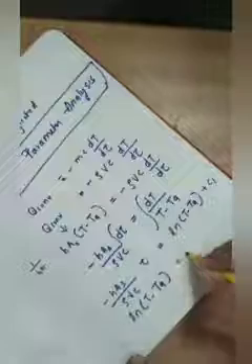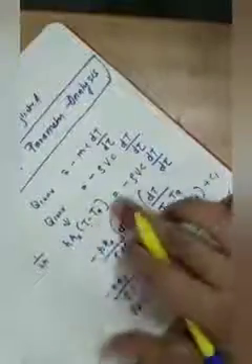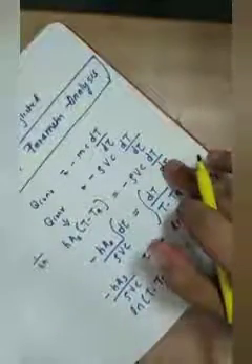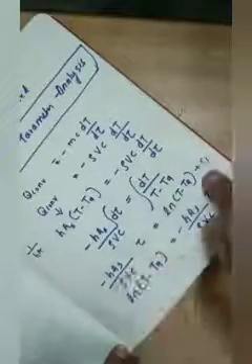On rearranging, log of T minus Ta is equal to minus h As by rho V c tau plus C1. Once again I will explain. This is a first order differential equation, we integrate it after separating the variables, and now we have got the solution as this.